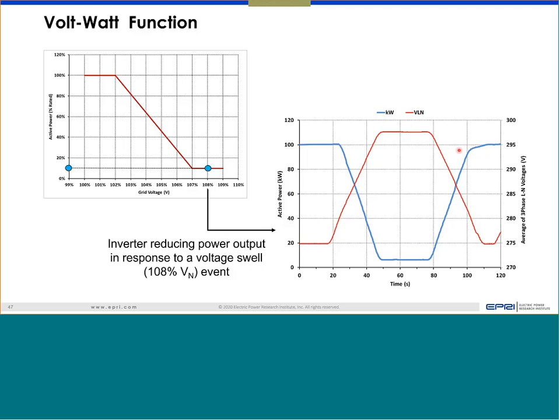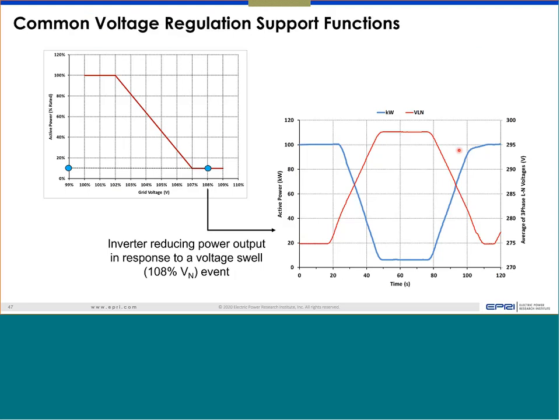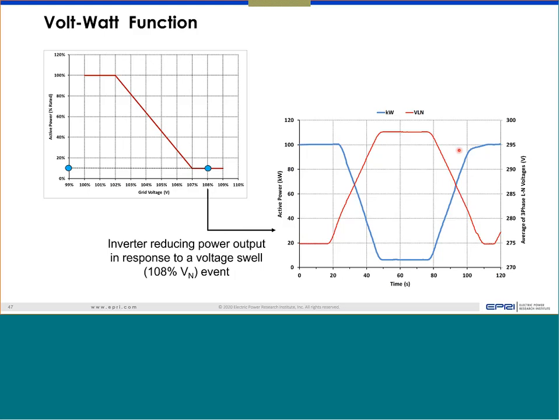So this behavior, this operation, is autonomous. Once you configure the volt-watt function, it will follow that curve and increase or decrease the power based on the configuration. Now, two things I want to highlight here. I mentioned that this is laboratory testing, and that's why we set 102%, which is very aggressive for a volt-watt setting. Normally, as a utility, most of your voltage varies 2-3% pretty regularly. It can go to 1.3%. Secondary voltage may go a little bit higher.